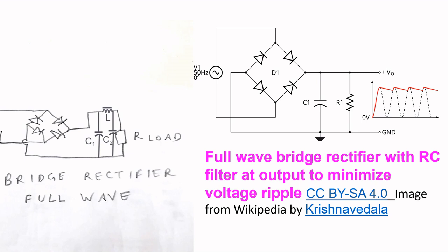Conversion losses occur in the transformer and the rectifier itself. A full wave bridge rectifier using 4 diodes does not require a center tapped transformer, but there is a voltage drop across 2 diodes instead of 1, as in the usual full wave rectifier, during each half cycle.